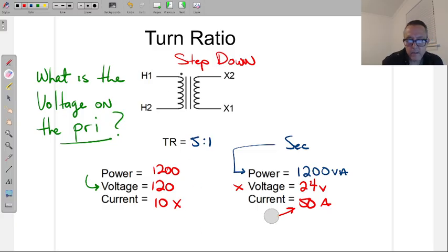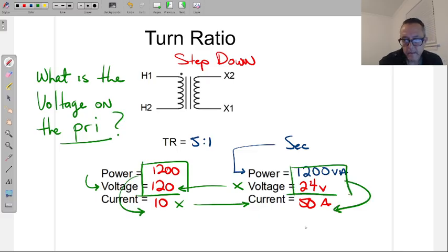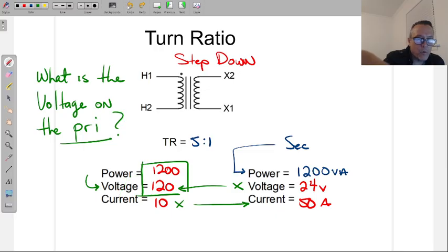So you could always do Ohm's law. Or you can use the fact that you have a knowledge of the turn ratio to do like we did. Multiply this one to get that number, and multiply that one to get this number. But at the end of the day, we could have just done Ohm's law to get here, and we could have done Ohm's law to get here. Either one would have gotten us the same answer. Now, why one versus the other? Because of just speed to get to the answer on some of these. Our exams are timed, but not in a crazy fashion.